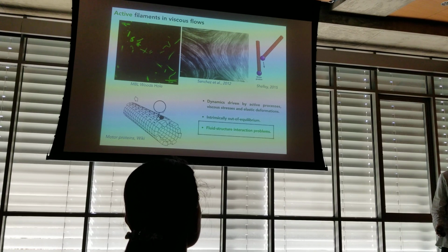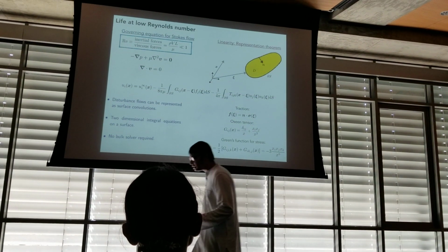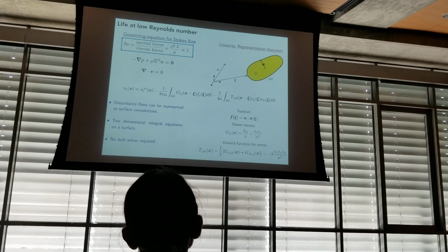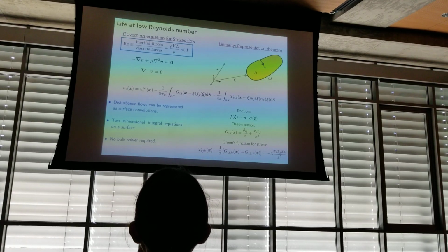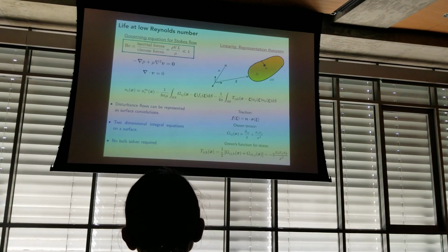in viscous flow. Okay. So I think I kind of mentioned, but all these problems are dominated by viscosity, where in the low Reynolds number regime, inertia is negligible. And in this limit of zero Reynolds number, the governing equations simplify considerably, and you have linear constant coefficient homogeneous PDEs, where V is the velocity, P is the pressure. These are the Stokes equations.